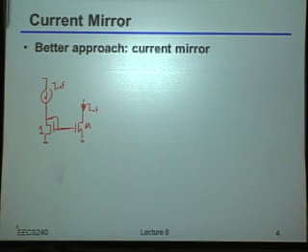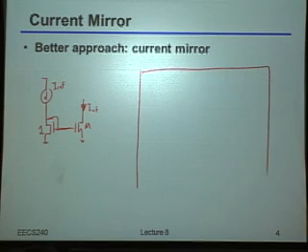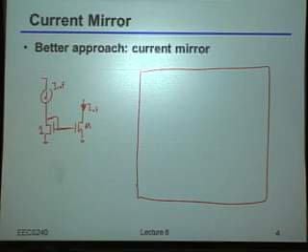Okay? So what will typically happen is, let's say you've built your chip, and it's got a lot of analog stuff on it. What will very commonly happen is, you'll put one pad in some place. You'll have that external current source sitting out on the board somewhere. And then internally, you'll just feed it into that diode-connected device. Okay?